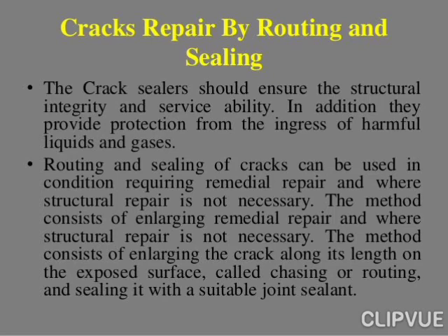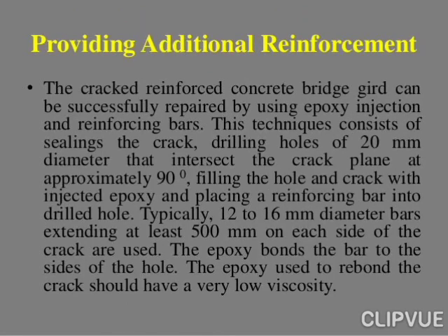The method consists of enlarging the crack along its length on the exposed surface, called chasing or routing, and sealing it with a suitable joint sealant.